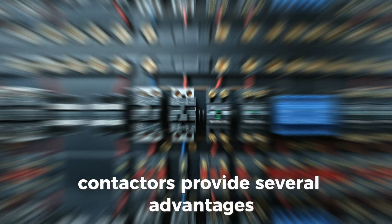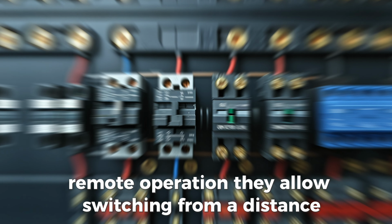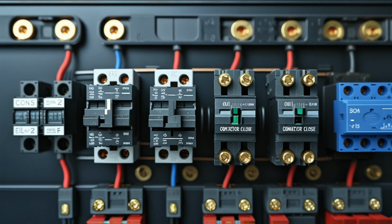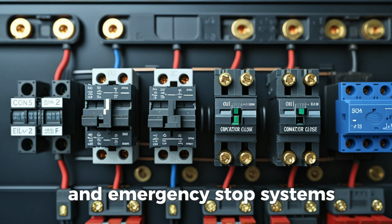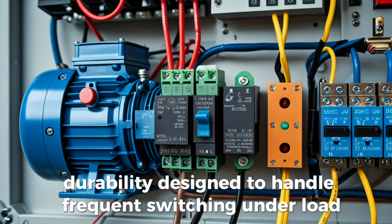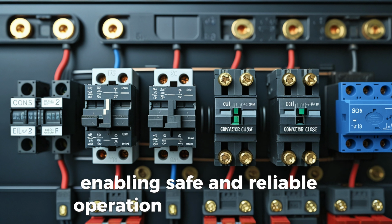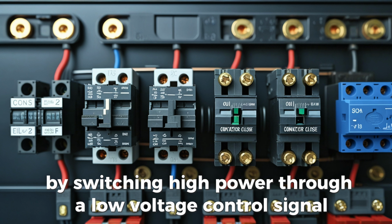Contactors provide several advantages. Remote operation: they allow switching from a distance. Electrical isolation: the control circuit is electrically isolated from the power circuit. Safety: contactors can be integrated with overload relays and emergency stop systems. Durability: designed to handle frequent switching under load. In summary, contactors are essential components in motor control circuits, enabling safe and reliable operation of electric motors by switching high power through a low-voltage control signal.